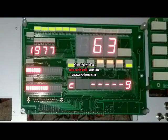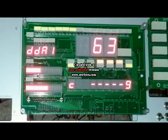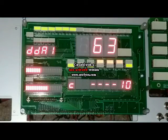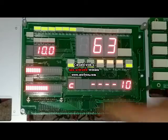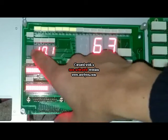Incidentally, as we'll see in a later video, any section of the display can be functional or connected as a show mode, so that if you have limited functions hooked up to the unit, you can just put those sections which aren't hooked up to real inputs into show mode. Another press of this will give us a direct display access mode. We'll talk about that in a later video as well, which actually enables us from the external computer to set or clear individual LEDs within the display. Another press of this button will put us back into trip meter mode. So you can see that we have, I've lost count actually, probably about 8 or 9 different functions that we can display on this trip meter.